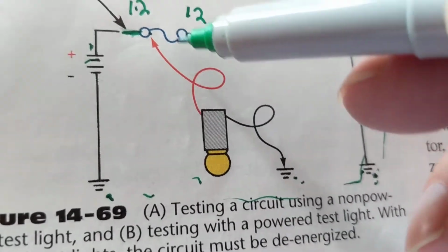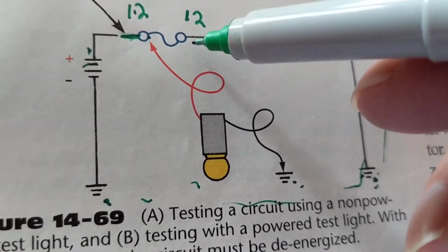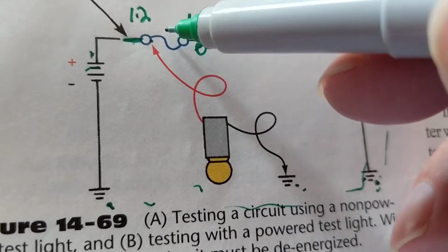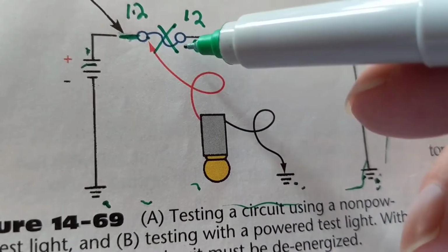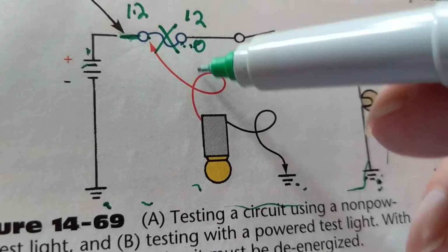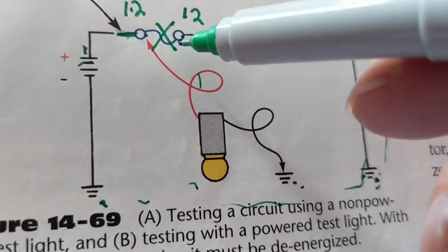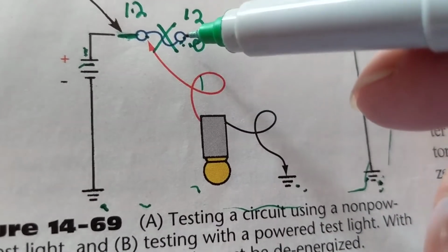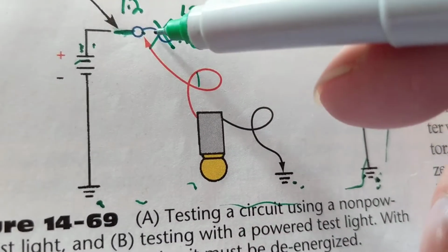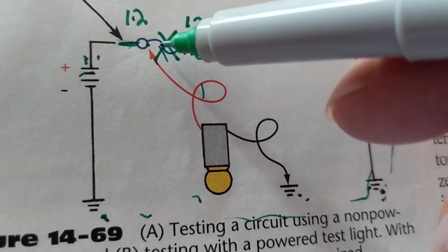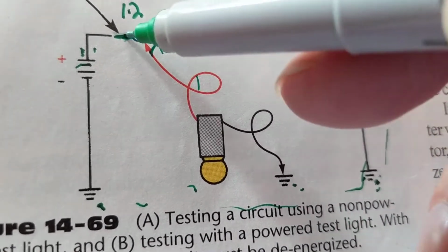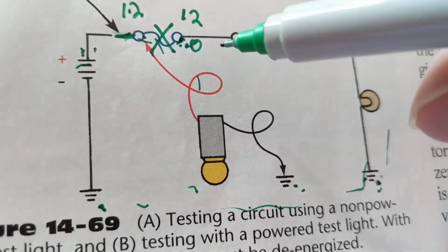And people ask me, why is it 0 volts? It's 0 volts because now when this opens up, it's not connected anymore. If we put a voltmeter over here, we're not connected to the 12 volts. So you can't have the 12 volts if you're not connected to it, because this is now open. When this is intact, we are connected by a piece of wire, so this is 12 volts.